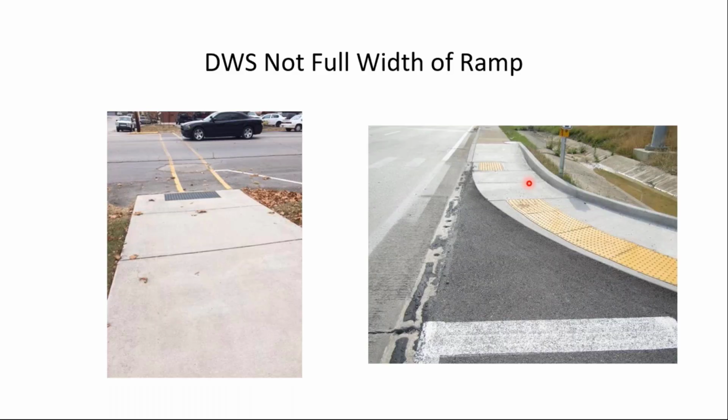And again, to repeat, a blind or low vision pedestrian relies on tactile cues. One tactile cue is a curb. That lets them know they're entering the street. And when the curb is missing, that's why we need the truncated domes. They are a replacement cue for the curb for the visually impaired. And like I say, I'm not sure what happened here, but that gap is a safety issue because someone could enter the street without realizing it.